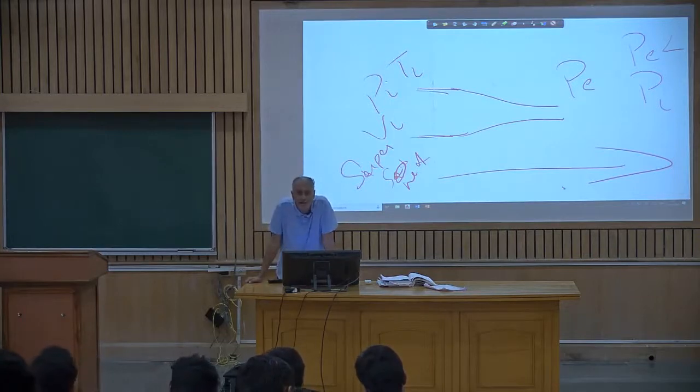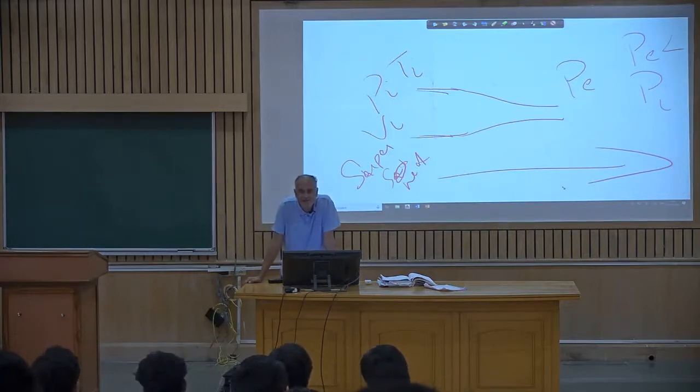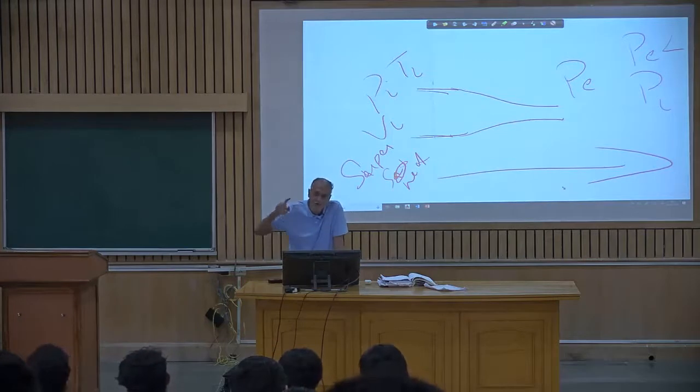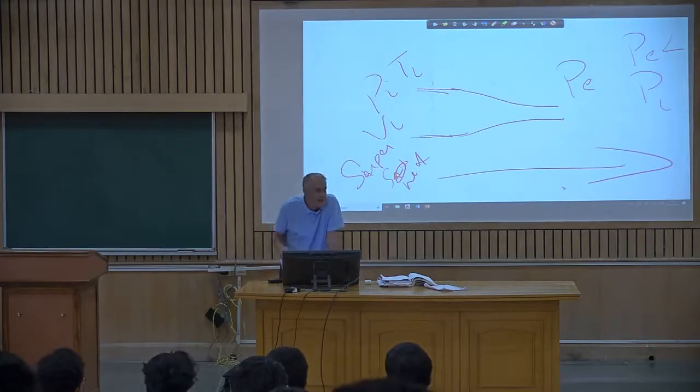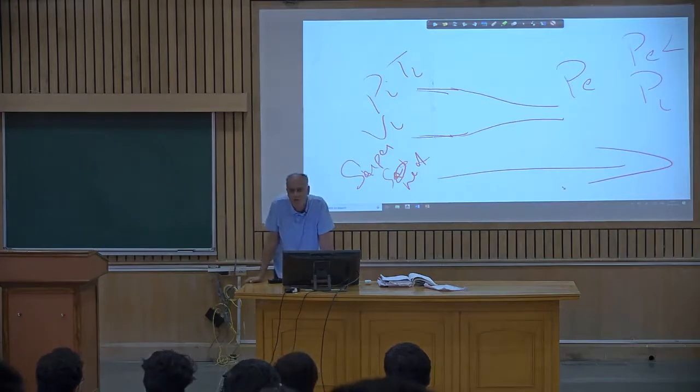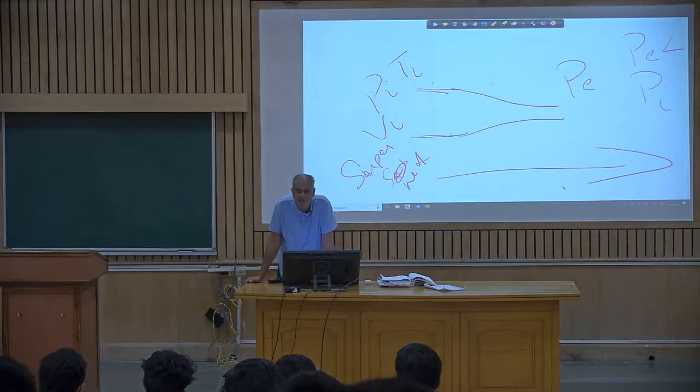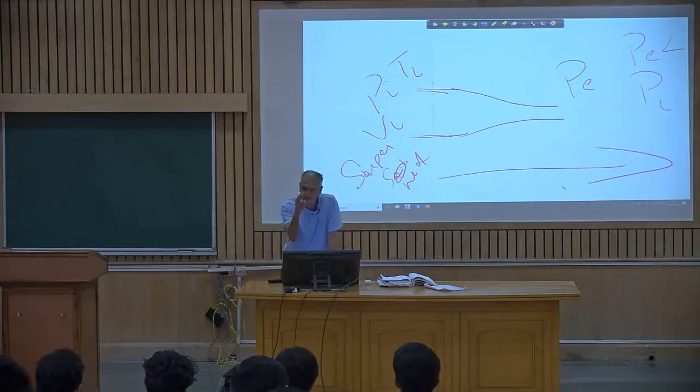So the flow work decreases, yes? So now, would it have to do more work to do the exit work? Because it decreased? Yes, it has to do more. So what happened? It did a lot of work and it lost its pressure. So what happens to a vapor which does a lot of work? It loses its energy, it loses its pressure. What happens to it? It becomes two-phase. Possible it might become two-phase.